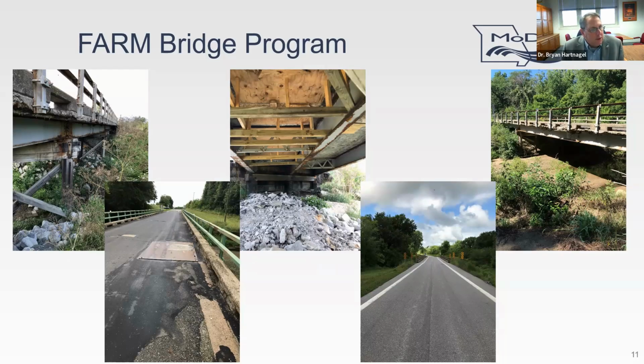Missouri gets pretty frigid too, and we put a lot of salt on the roads. So, this is some of the deterioration you see with that. Down here, bottom left, we have a plate. The deck is in such poor condition that sometimes the fix is to put a plate over the hole. Top middle, full depth deck repair, leave the forming in place because you may need it later.